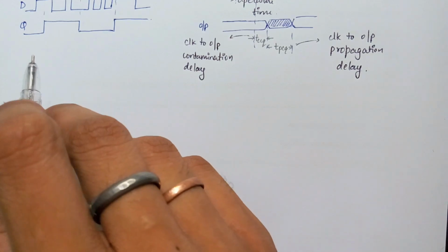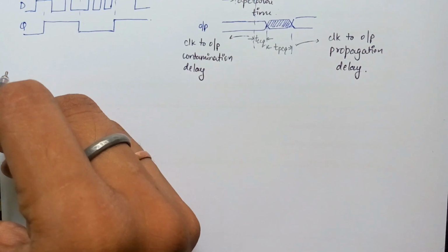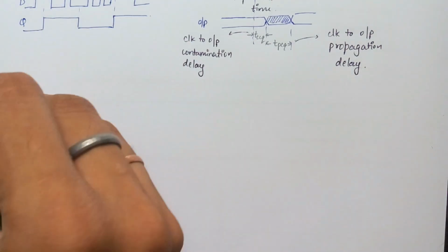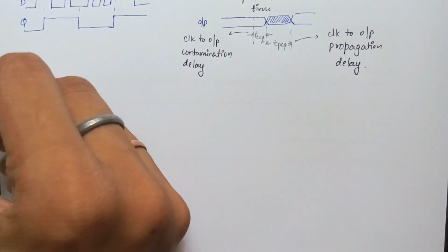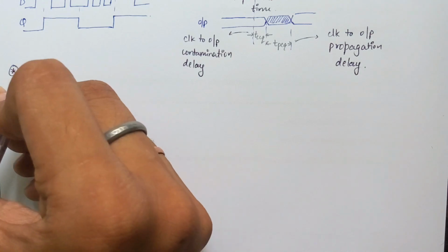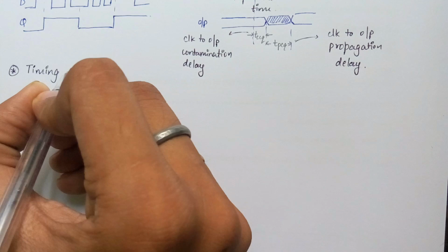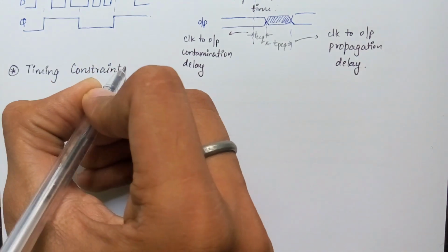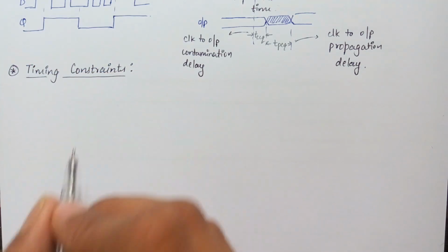Now we understand the basic terms. So let's see how we decide the clock frequency of a digital circuit. A flip-flop samples its input only at edges of clock. So if we increase the clock frequency, we can make our circuit work faster. But we can't go on increasing the frequency blindly, because the delays of the combinational and sequential circuits used impose some constraints on the maximum frequency that can be used without the output going unpredictable.